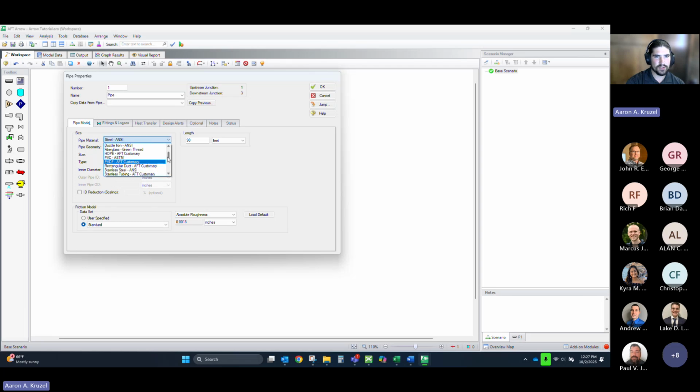So you can adjust to a user specified pipe. You can specify what type of pipe is being used and dictate the size. Generally, cylindrical piping is pretty typical, but then you can choose the inner diameter. HDPE piping, for example, doesn't have the largest selection, so if you had to account for a very large HDPE pipe size, you could add that in.